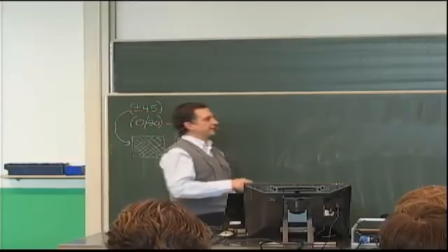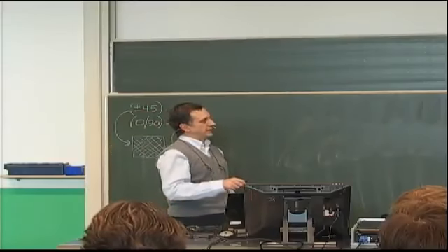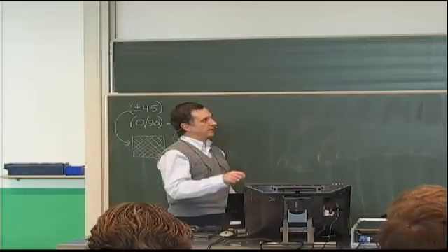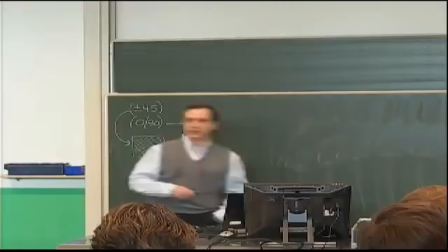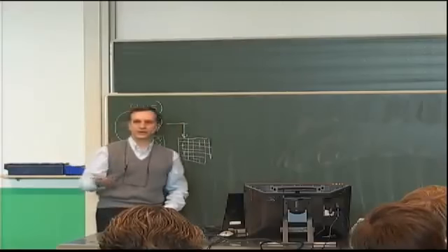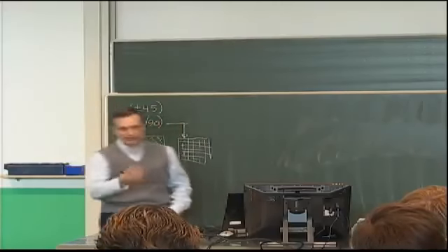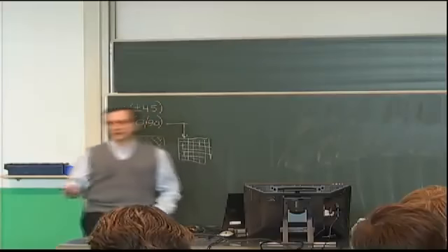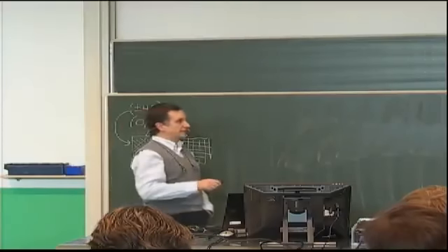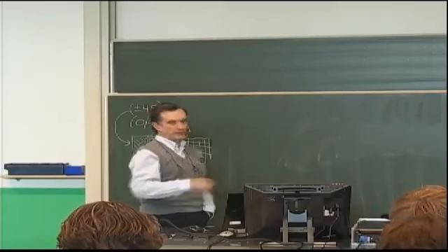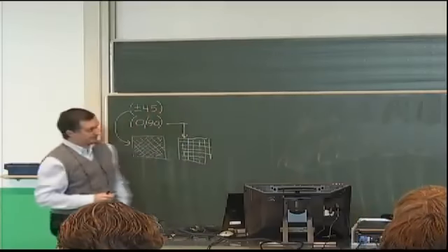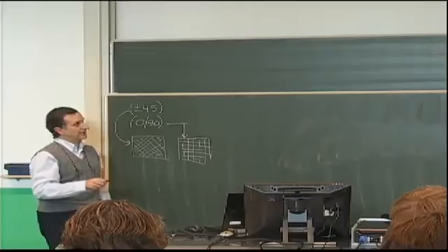There's no point in reinforcing from here on, which would correspond to some point in the middle of the plate and moving towards the bottom end, because the stress there has already reached the far field stress. So that's the one that you would design for anyway, and there's no point in reinforcing there. But there is definitely a reason to reinforce from 0 to about 0.3 or so, at least for this specific laminate and for this stress.